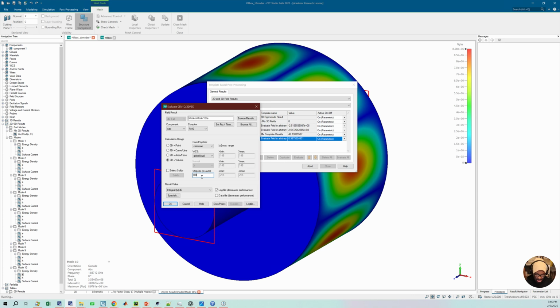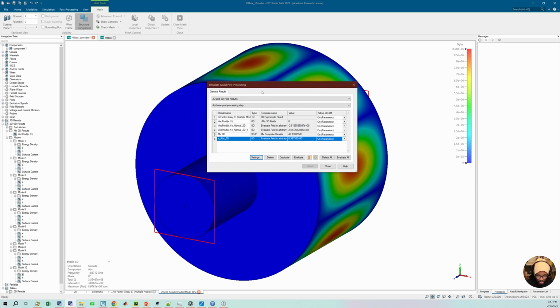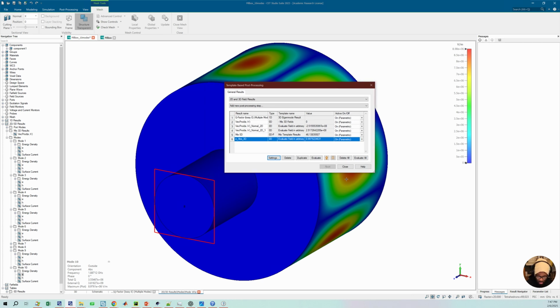The result changes a bit, but I haven't checked how much it changes, or if it actually gives improved results, because ultimately I think the points that you do not have are interpolated. And if your result, depending on your mesh, is already not very fine, I don't think you can improve it by taking more points. Instead, you should refine your mesh. So that's one part of what I wanted to show.